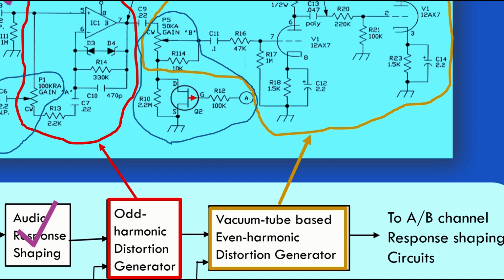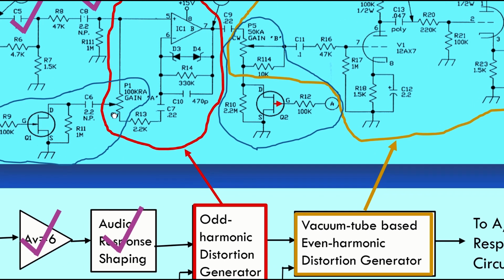First, a quick overview. Remember, signals coming in here at the upper left. There is a potentiometer here. And if we turn that potentiometer all the way up, meaning fully clockwise on the front panel of the amplifier, then this tap point is at the bottom. And the circuitry over on the left here is an analog switch. We'll cover that briefly in a minute, but just imagine that this point right here is now an AC ground at this node at the bottom. That means that R13 is connected to ground.